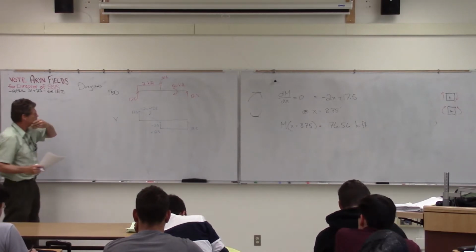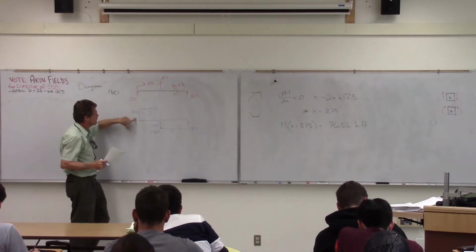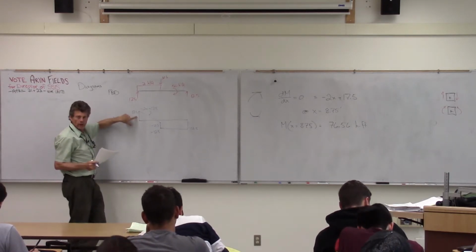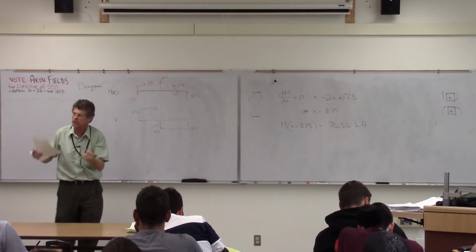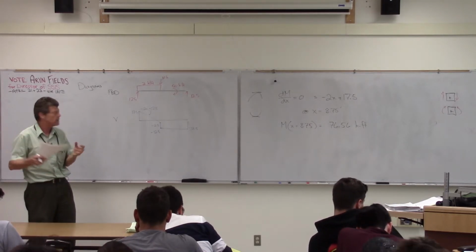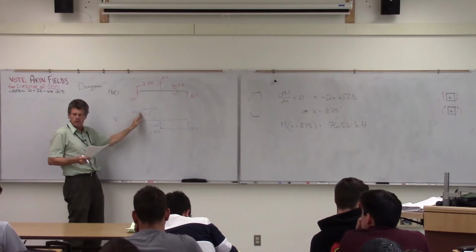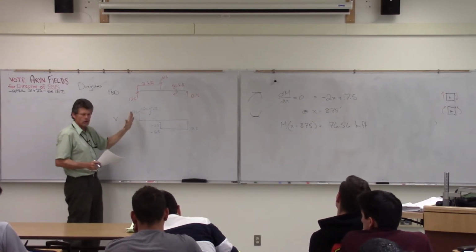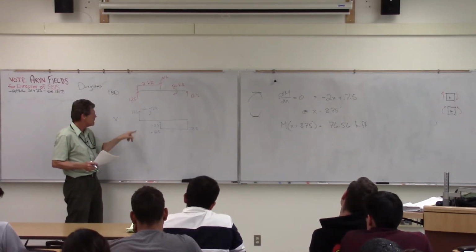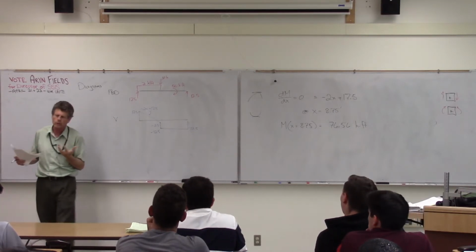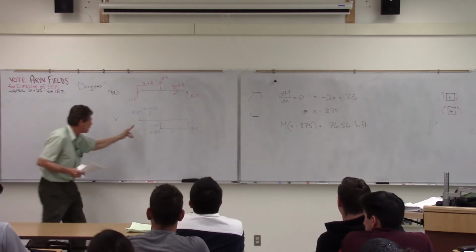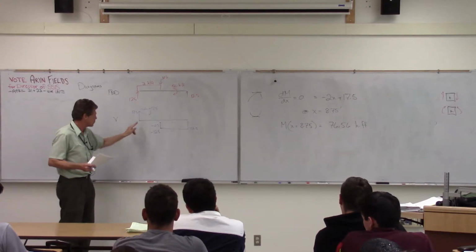Now let's think about what we're seeing here. A jump in my shear diagram. Again, remember what shear is. It's just simply vertical equilibrium. So when I make a cut very short here, it's not going to see much distributed load. As a matter of fact, if I take it just past the 0 point there, the only thing it sees is a 17.5. So yeah, it's going to start off with a big jump there. It goes from 0 to 17.5.